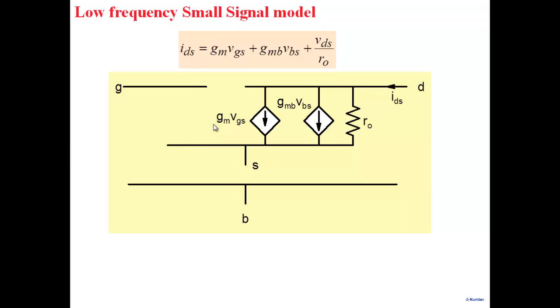So for any amplifier, any circuit that is given, where you want to do a small signal analysis, all you have to do is take that transistor out and substitute this particular model. We have done enough of these small signal analyses with bipolar. So the analysis here is also very similar. Note that the model is the same: GM VGS and R0. In fact, it is simpler, I would say, because there's nothing on the input side. So all the things that we did, with the knowledge that you have, you can very readily go ahead and analyze any of those differential amplifiers.